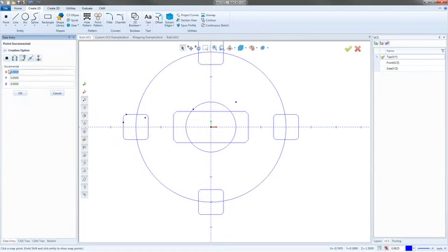So if I say let's move over 1 by 1, same numbers, what should end me right there. If I go ahead and click on this, let me update that. There we go. We will see it's moving over 1 inch and then up 1 inch, just like that. So the incremental lets me choose kind of the 0 location, and then from that 0 location that I choose, I can move a specific distance in X, Y, Z, wherever I got to go. And real nice function.